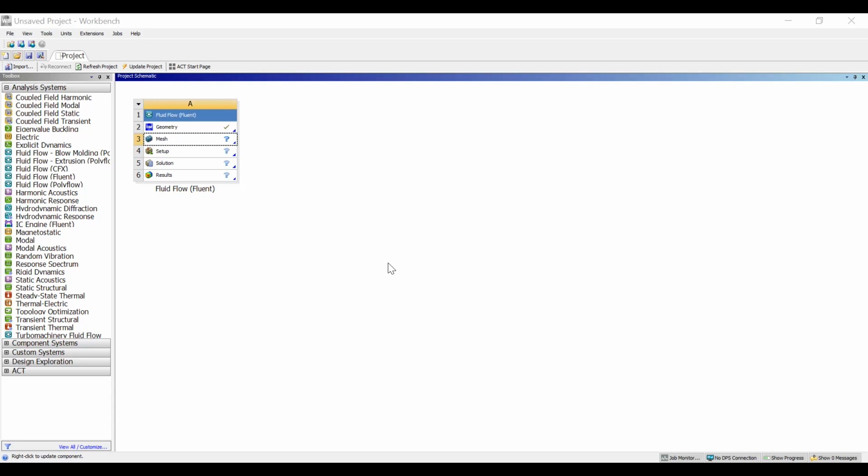So we need to select our geometry again. Let's go. We got to change this to face. So we want our face. And then our element. Oops, did not apply that face geometry. Apply that. There we go. Oh no, sorry, I'm mistaken. I was getting ahead of myself. No, not the face. We want edge sizing, as I told you before. So we're going to go ahead and click on the circle. There we go. Now we have our edge sizing from our interior. So we're highlighting there. Okay.